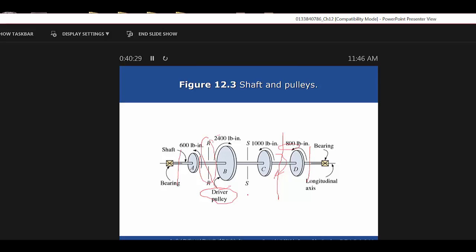What you would typically do is just leave that shaft the same diameter as what you're going to have on the other side of those two pulleys. And that's what you have to have, because you have to be able to get that pulley on there and hold it in. So that wouldn't necessarily fly, okay? So that's what's going on there.